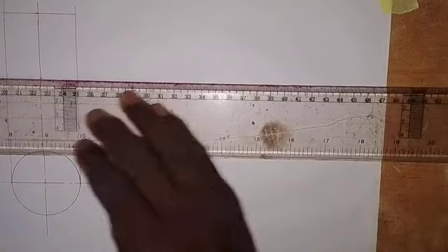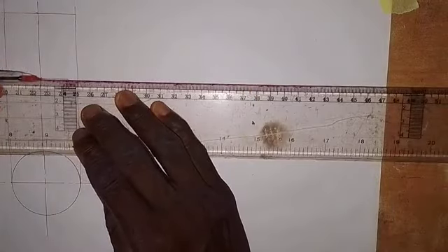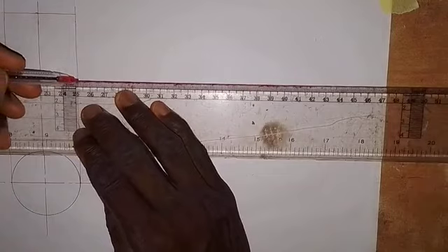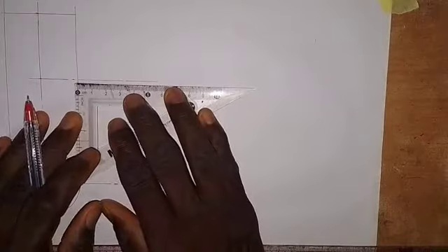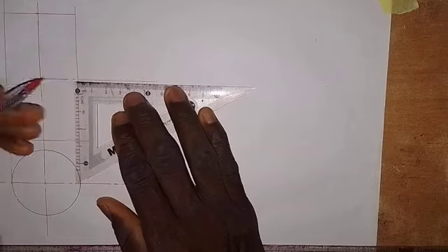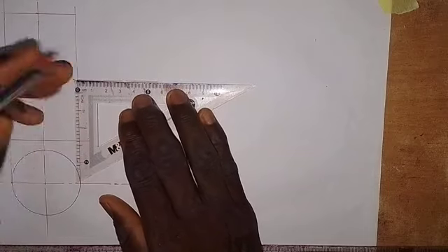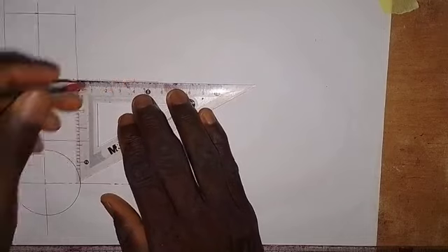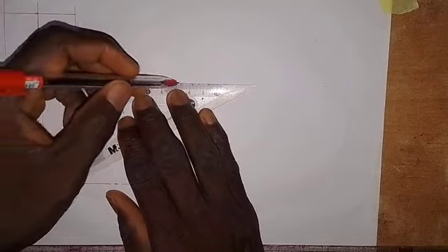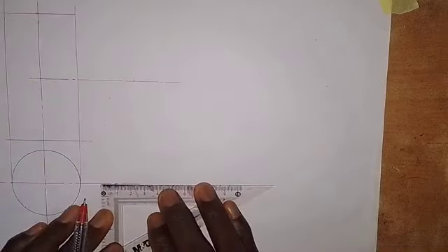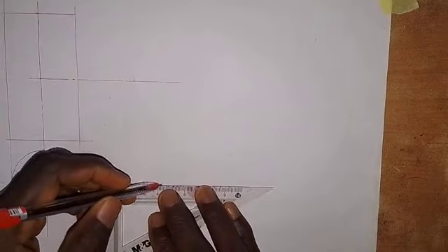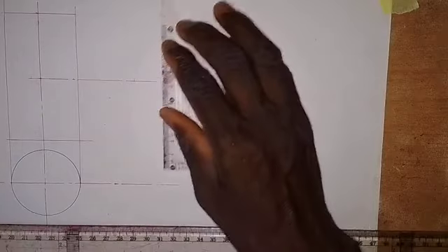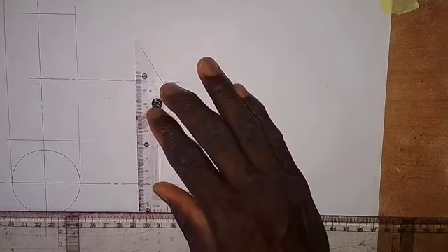So we draw a horizontal center line through this point, going to this side. Now we have this. On this line, I take a measurement of 45 millimeters from this point on the vertical cylinder, from here to this side. This is 45 millimeters. Let me extend this a bit to this side, and also come down here and extend this horizontal center line a bit. What I'm going to do now is draw a vertical center line.